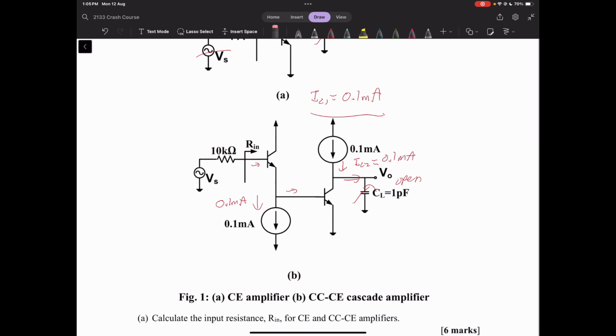And that is a really important skill to develop in the 2133 final, is making valid assumptions that simplify your working out. So my advice would normally be, if something seems quite difficult and you have a large resistor or small currents, you can just assume that resistor is open. You'll often make the assumption that R out is too big, so it's an open circuit. That's a very common one, but these are very good. And you will still get full marks if you make these approximations as long as they are reasonable.